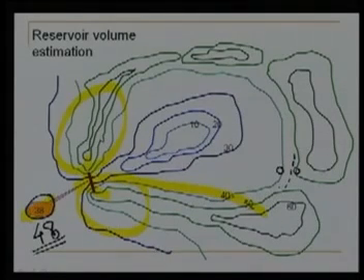Now if we keep drawing this contour everywhere, it will form a closed figure which will end at the edges of the dam. So from the top of the dam, we follow that contour of 48 meter everywhere. If there is rainfall in this catchment, that entire area will be full of water.